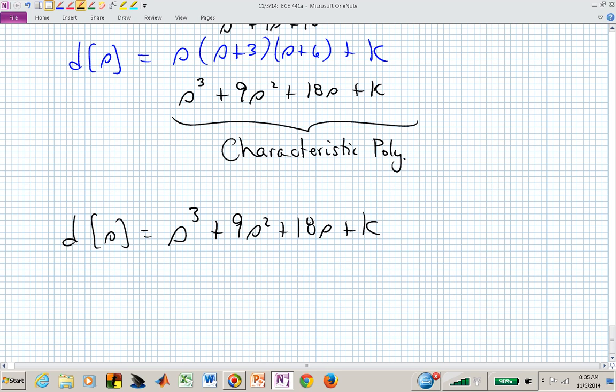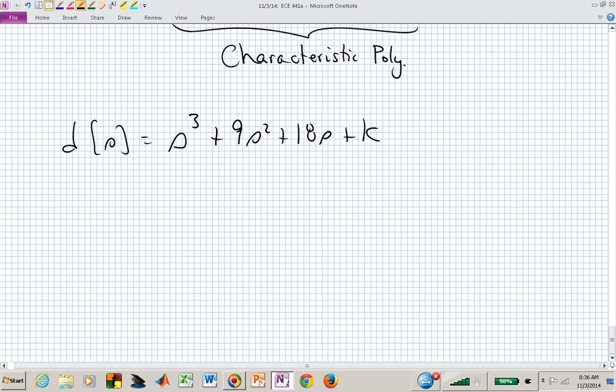We're trying to find the gain or the values of s when they're imaginary. How many values of s do we have? 3. We want the 2 that will be imaginary. That third one's going to go off to minus infinity. But we want to find when does this have imaginary roots and find the k that causes that to happen. Really, we're more interested in the s values, the j omegas. We wanted to find where our root locus is crossing the imaginary axis.